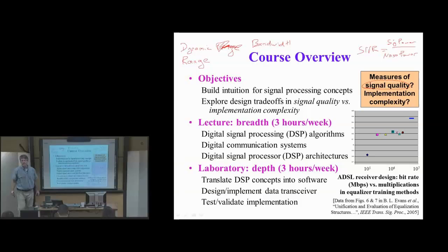Bandwidth. And we can take bandwidth and relate that to bits that we can communicate. There's a direct relationship. But there are other ways we can think about bandwidth. It doesn't have to be a digital communication stream. What else is there for signal quality? Go ahead. Or probability that there will be an error, maybe like bit error. Yep, probability. So in a communication system, it's the probability. So signal quality is the probability of correct detection.